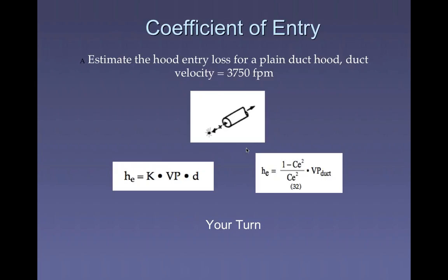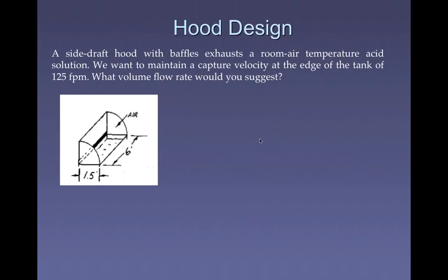So you need a static head pressure of roughly 1.6 to account for the 0.81 loss and the 0.88 velocity pressure. That's the whole idea here. The static pressure has to be high enough to account for the velocity pressure you've created and for the loss going into the hood.